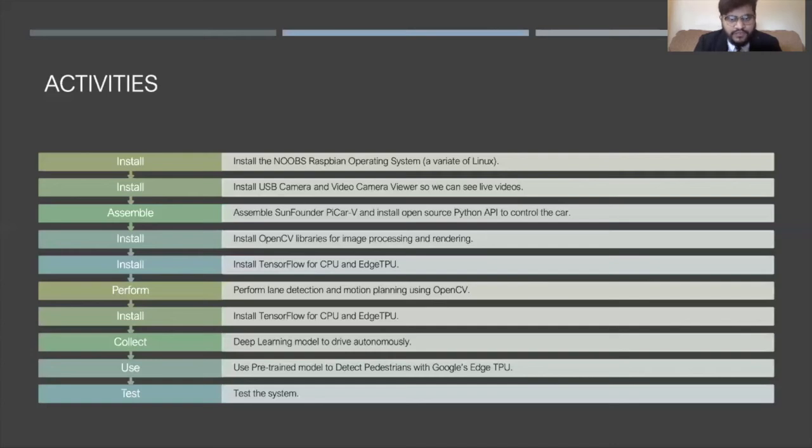The procedure of installing the server of the application on the Raspberry Pi is mentioned in the report. And then there are general applications for any operating system. Personally, I'm using Mac OS, and there's a Windows version as well. You can just type in the IP address of the Raspberry Pi, provided that the Raspberry Pi has a Wi-Fi driver and is connected to the Wi-Fi network. It will establish a connection to the Raspberry Pi operating system from our computer.